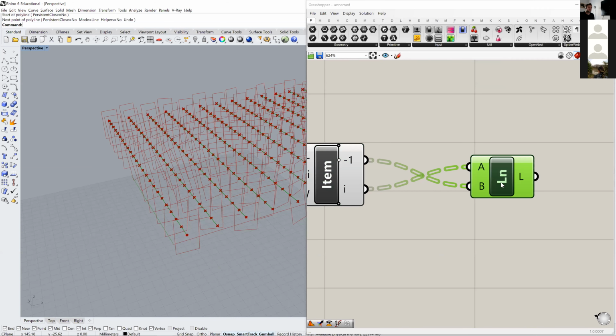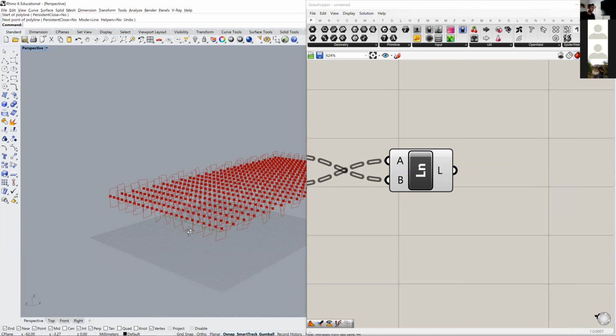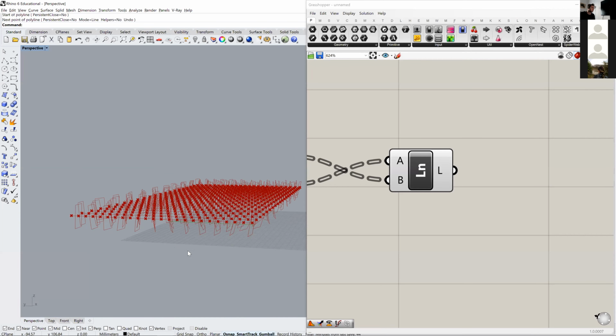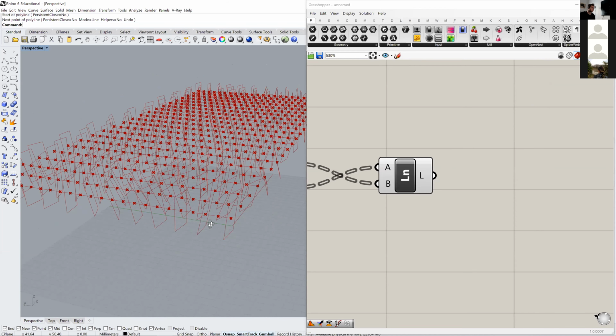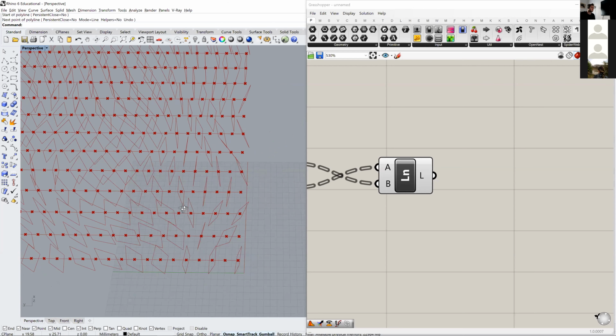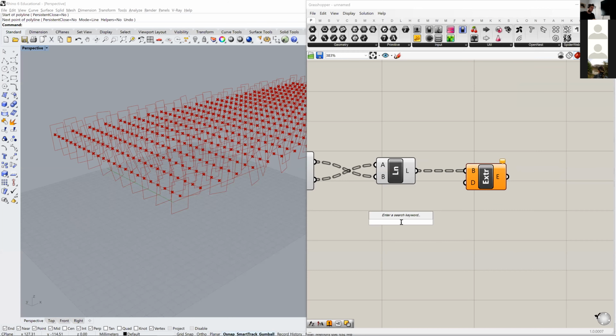and now I can just extrude this line vertically downwards. I think it will fit this operation. Okay, so extrude curves and surfaces along the vector. So we need to set the direction.